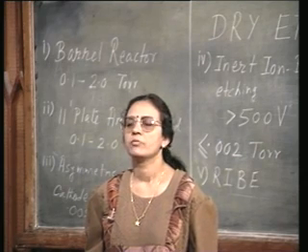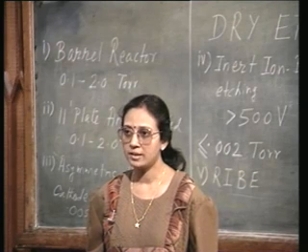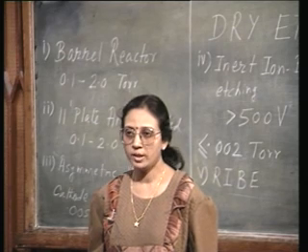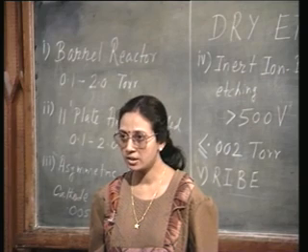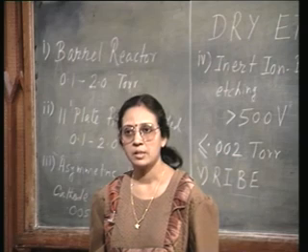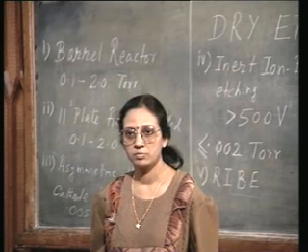Suppose for various devices I need to etch in the active region. Whenever you are having bombardment with high energy ions, it is going to create some damage, and in some cases this damage can be unacceptable.